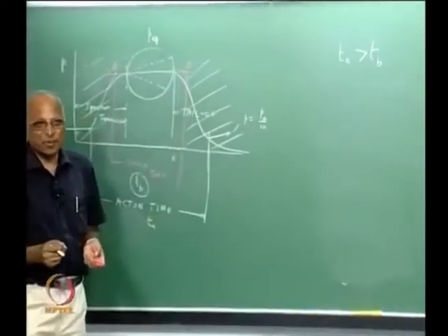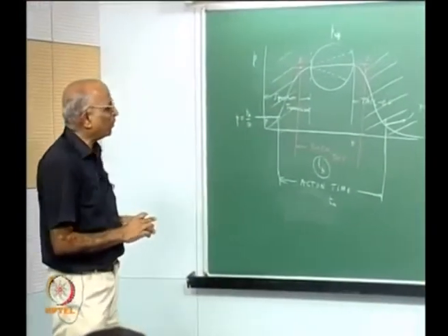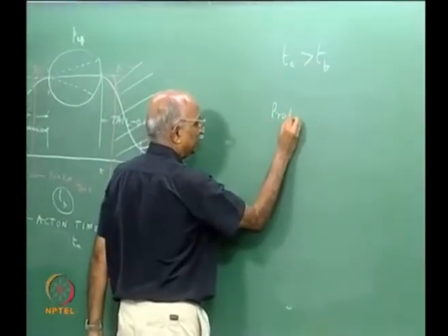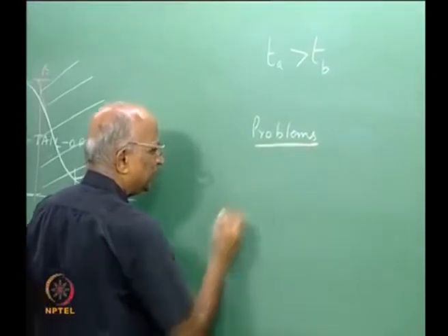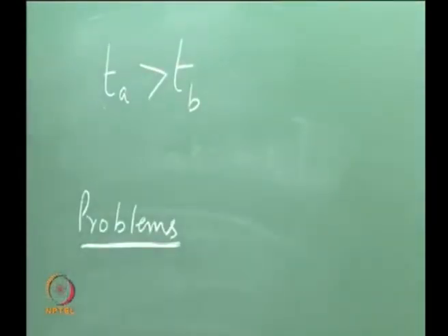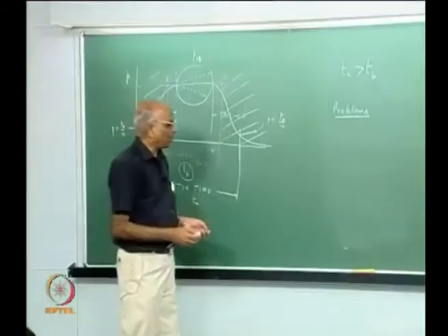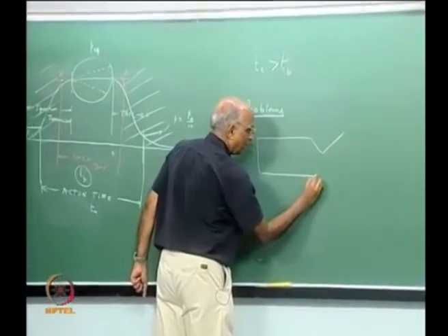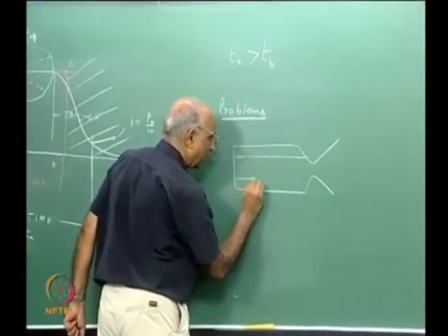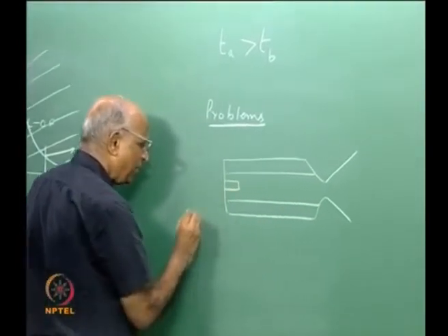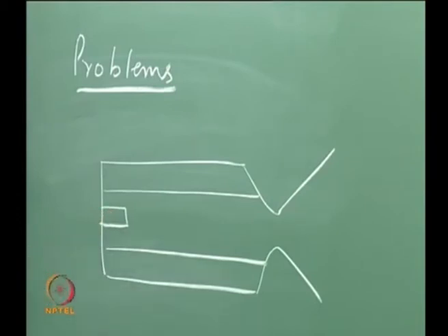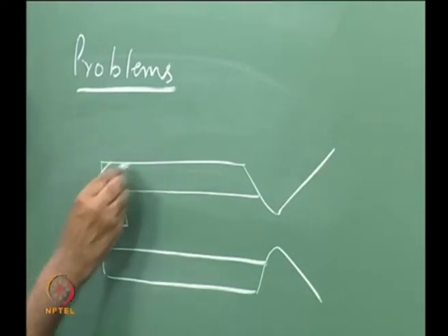Well, this is all about solid propellant rockets. Now let us go back and examine one or two small problems we can have in solid propellant rockets. Whenever we make a rocket, let's say I make a sketch of a motor, it's radial burning, I put an igniter, and we told ourselves the other day most igniters are pyrogen igniters, because the solid propellant rocket motors are quite large. I have the propellant here.